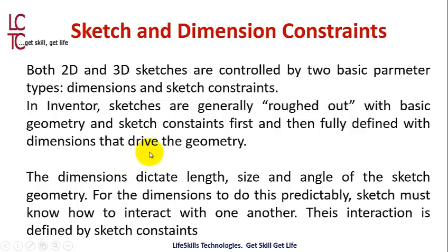So, another thing I want you to note is that Inventor is dimension driven. It is dimension driven. Once you know the dimension, the length will change as you enter the dimension. You don't need to redraw anything. All you need to do is change the dimension.